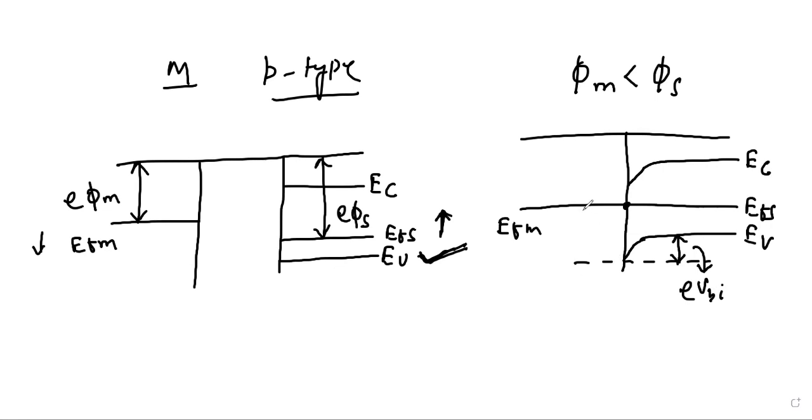And the phi B0 will be this. From the metal side, what is the barrier height? So this we will consider in the valence band, we will consider for P type. So accordingly, your ideal barrier height will be this, E phi B0. This is for P type. So now the depletion region is created over here for P type, and phi m less than phi s. Similarly, we can do for metal and P type where phi m is greater than phi s.